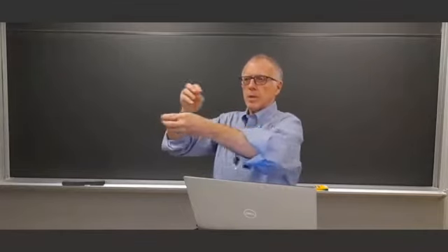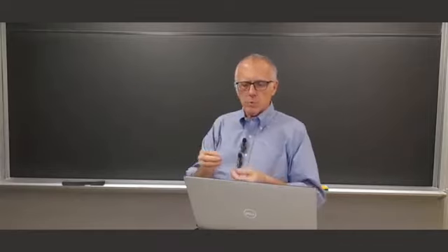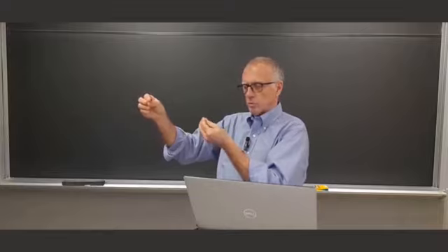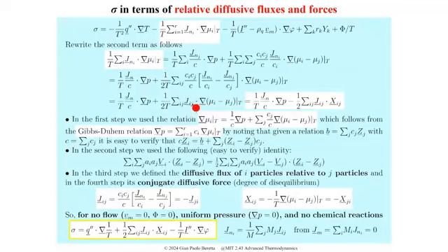So there is a crossing of the flows. So here J_ij is the flux of water vapor particles with respect to the motion of the air molecules. So it's a relative flux. And also these chemical potential differences that are written here, we can think of them as the conjugate, relative forces.